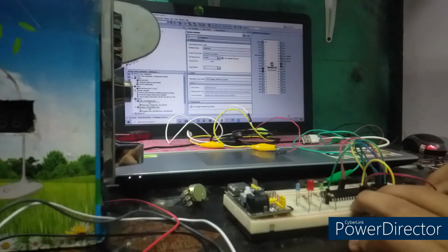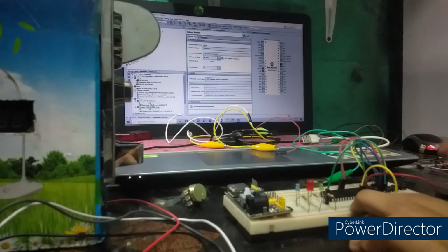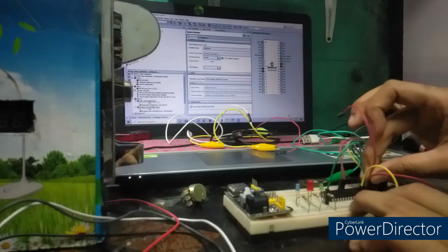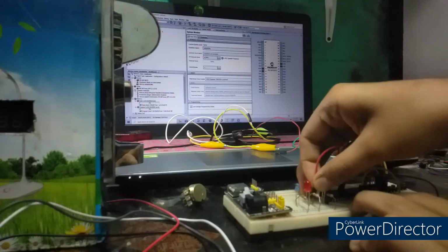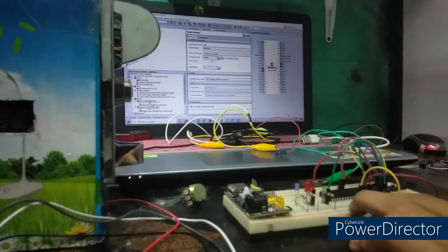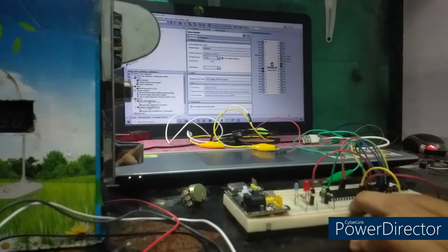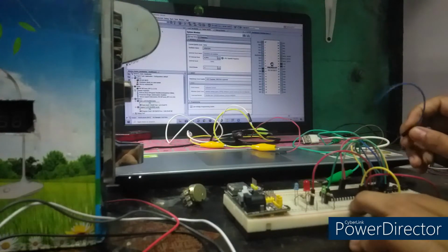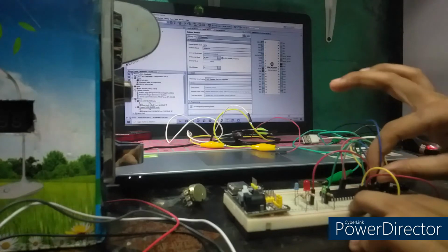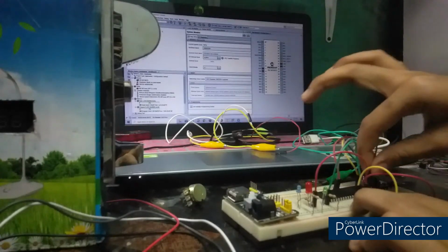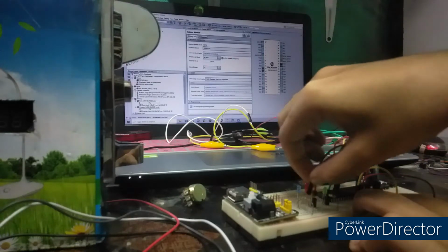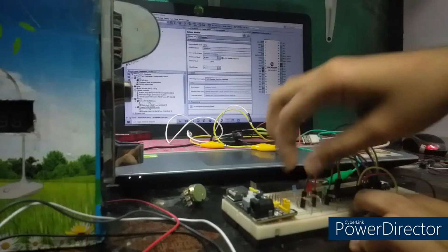And then the L5, our 5 peso LED indicator, is connected to our B1 or the 34th pin. So for the red LED, we will be using a red wire, connected to the positive terminal of our red LED here. And then the blue wire will be connected to our blue LED, which is on the 35th pin of our IC, up above the red wire. So red wire, and then this blue wire to the positive terminal of our blue LED.